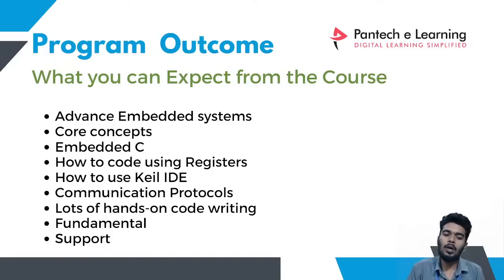We are going to code using registers, because when we use registers, you will know the backend process. When you take Arduino or NodeMCU, if you want to send some data in UART communication, you just call a function, Serial.print, so you will not understand what the background process is.